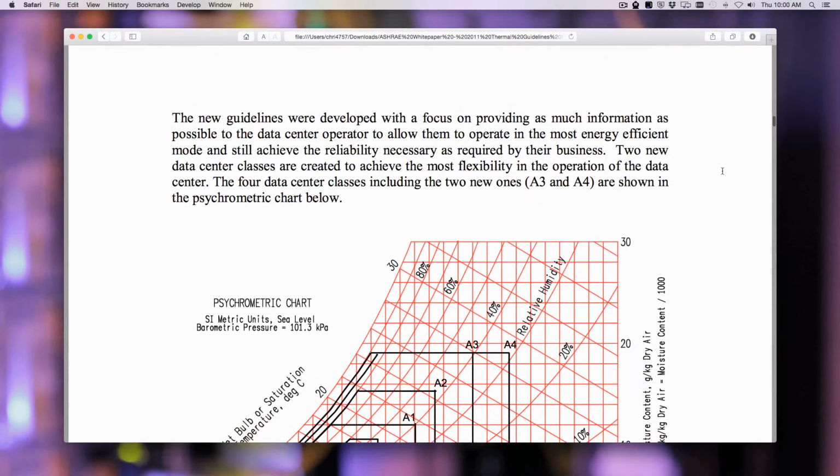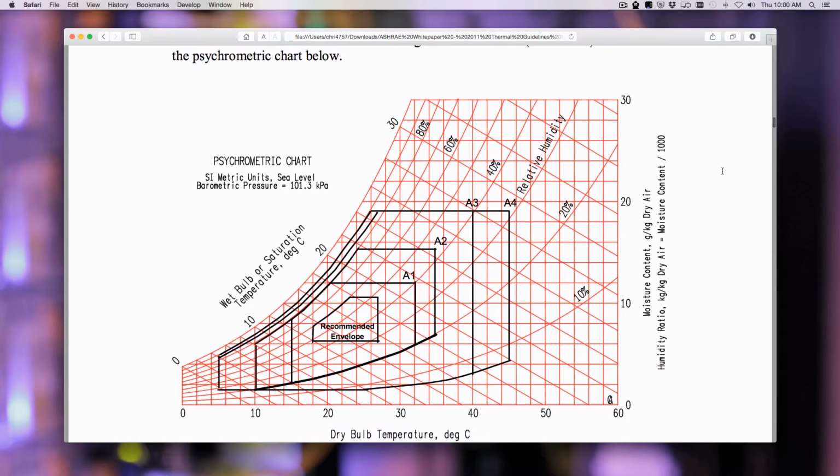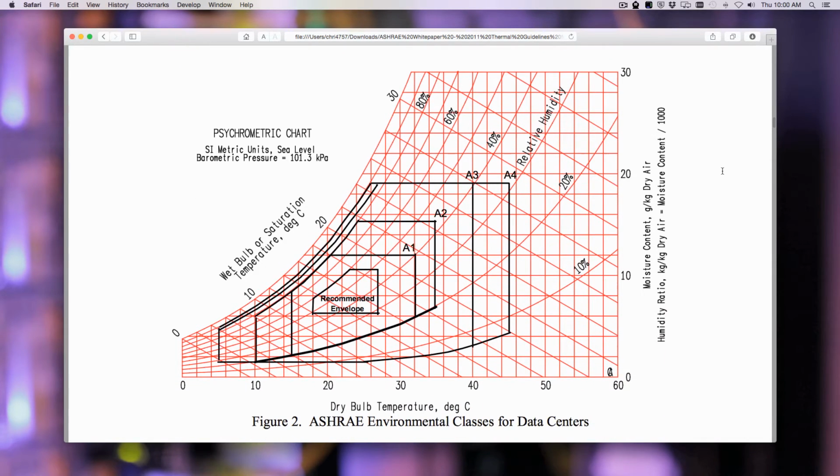And in this case, we're using indirect air cooling technologies. If the temperature in the room is warmer, then that increases the possibilities of free cooling using outside air, and that's a change that has been taking place over the last 5 to 10 years.